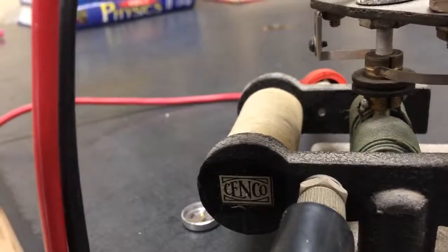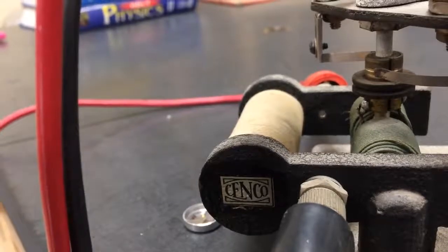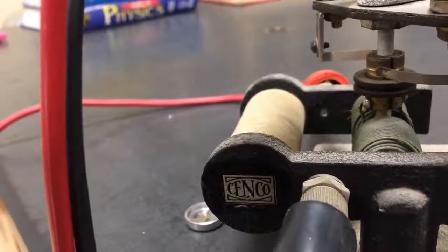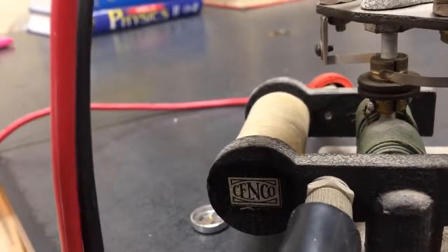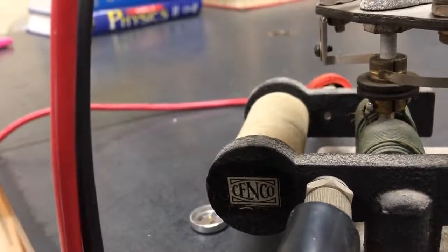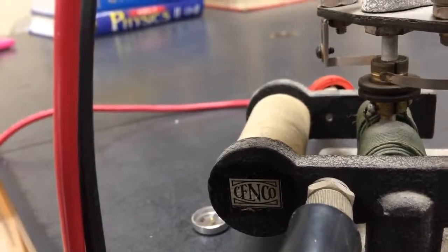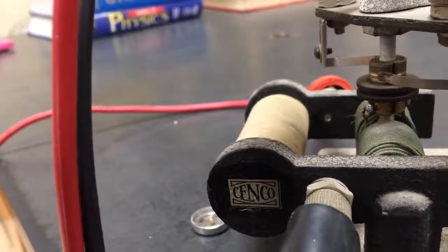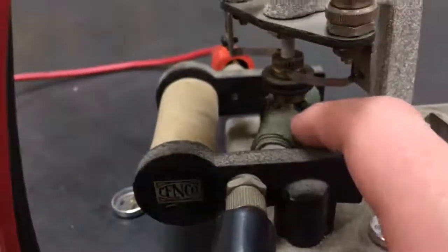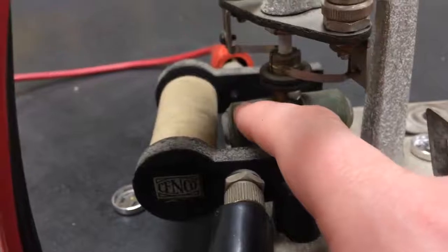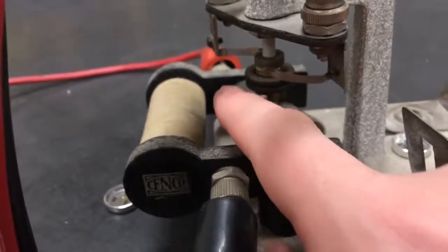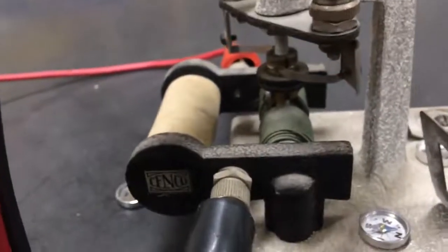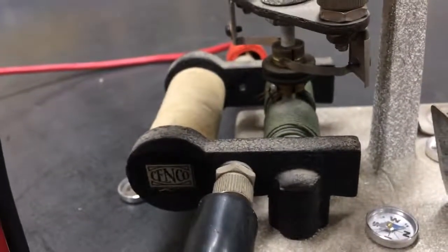And that means it's constantly switching back and forth whether positive or negative is touching each side of the jacket. And that means the coil is reversing the direction of its current, just as if it was alternating current. And that means that we're always getting pushed in the right direction, because after we've gone around once, it flips, current reverses, so now it continues to push in the direction we want. So it's on all the time instead of half the time, like the previous motor.